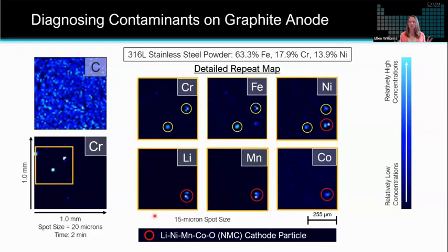And again, because you have the advantage of measuring the full chemistry down to the parts per million constituents, you can get a very detailed picture of what your material is. That can be very helpful when you're trying to figure out, okay, yes, I know I have a contaminant here, I identified it with an optical technique, but what actually is this? Which tool did this come from? And that's where this technique adds a lot of value, by giving you that full chemistry picture of that contaminant, helping you diagnose where it came from and prevent it from occurring in the future.